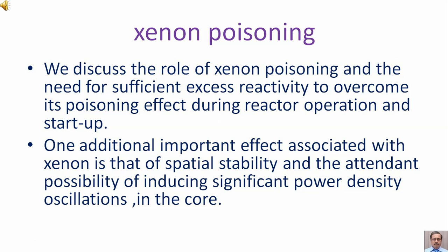One additional important effect associated with xenon is that of spatial stability and the attendant possibility of inducing significant power density oscillations in the core.